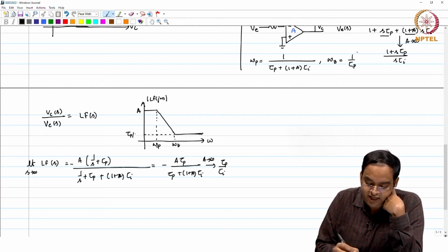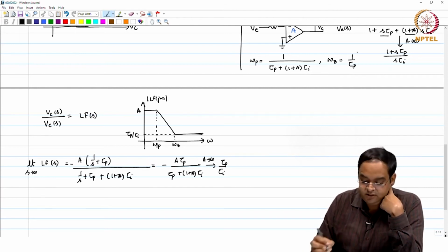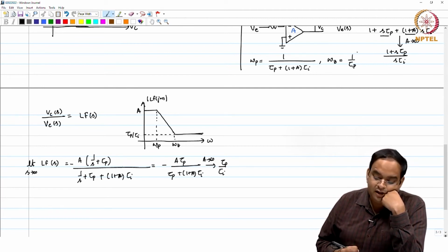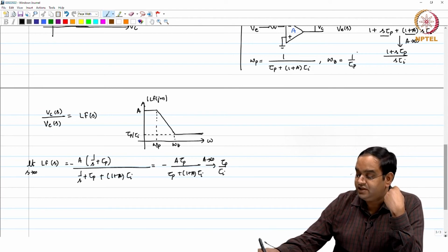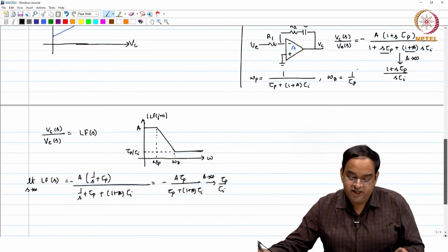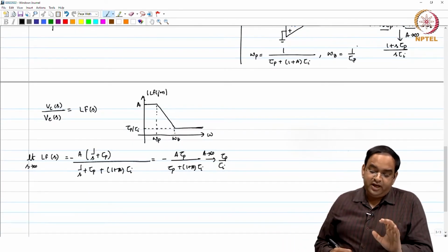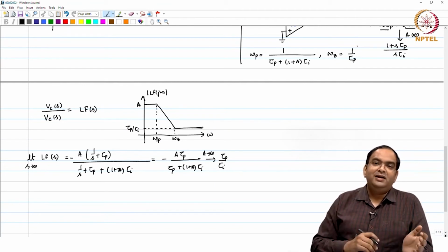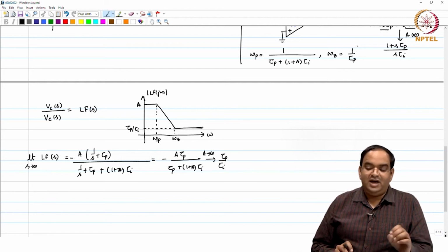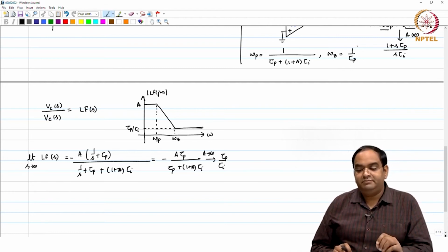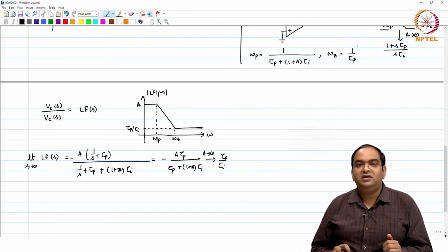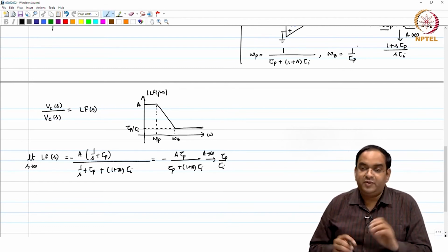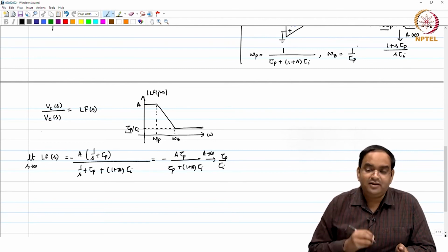So, this is what I have here approximately, if a is assumed to be very large, because for an amplifier a is in general pretty large. So, what you see here is you do not have an ideal integration path. You have an integration path, but it happens to be non-ideal, right, and then you have a proportional path with a constant gain like this.